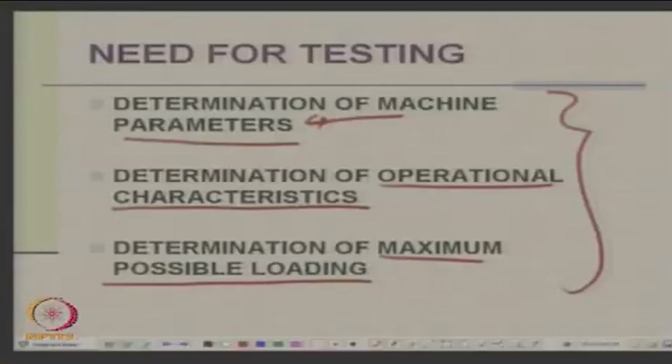So, you overheat it. As a person is supposed to carry a certain load on his head, if you put more load on his head, he will collapse, or fall sick, or break his bones, or whatever it is, right. So, something happens to the motor. If you increase the loading, it will overheat. There is a capacity of the windings to carry current, and also there may be magnetic field distortions and various things. There will be more losses also. So, all these things do matter. Okay. So, you would like to know all these things by actually conducting the testing.